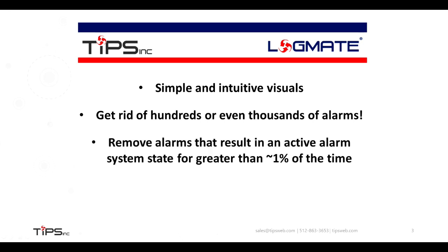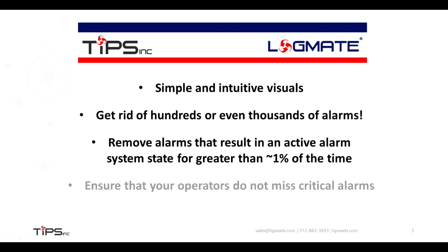ISA 18.2 recommends removing alarms that result in active alarm states that are in your operating system for greater than 1% of the time. It's not just alarms. You can also ensure that your operators do not miss critical alarms. This is where our ACE reports come in.